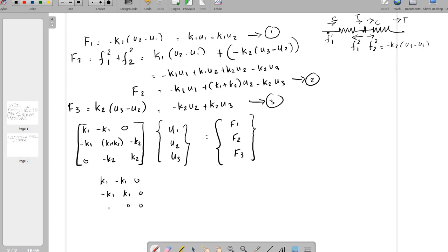So we can easily divide the above equation as K1, minus K1, 0; minus K1, K1, 0; all other elements are 0 for element 1. Here it is U1, U2, U3. I am separating the above matrix, that is here F1 of 1, F2 of 1 and 0. The third force component is 0.